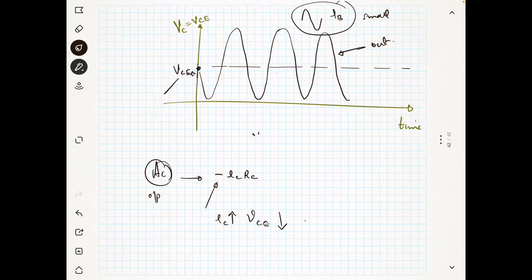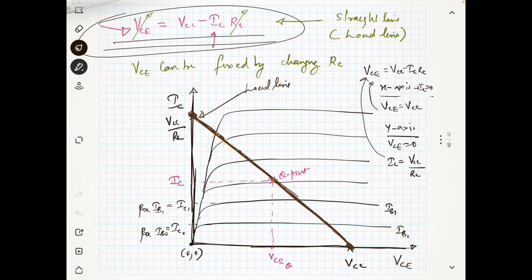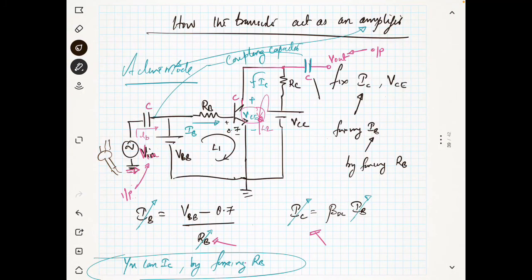It contains the DC part, and you have the AC part. So you have AC and DC in the output. But when you use a capacitor here, what will happen? You will be getting only AC at the output, because the capacitor will block all the DC. So the function of the capacitor is to block the DC.